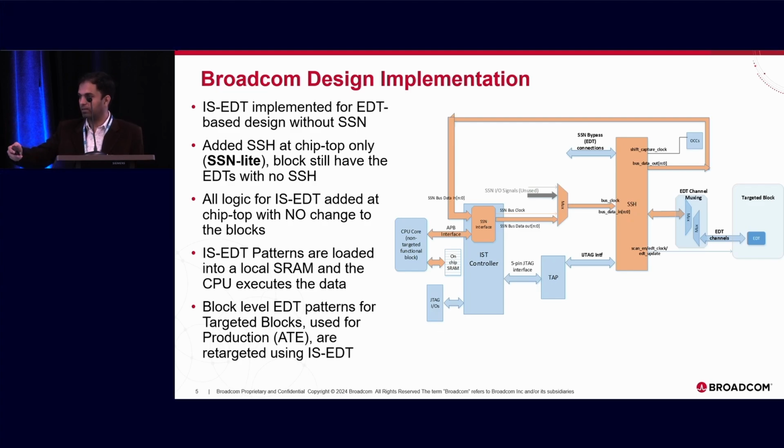The way we are targeting, let's say in one in-test mode, one of the ATPG modes, we have, let's say, 3 blocks, 4 blocks. That grouping remains the same. So we are just reusing the patterns that we would use on the ATE for the IST. We are targeting the exact same patterns which we used on ATE for the in-system. That is a good feature, because there is a one-to-one mapping between the results we have on ATE and what we get on IST.